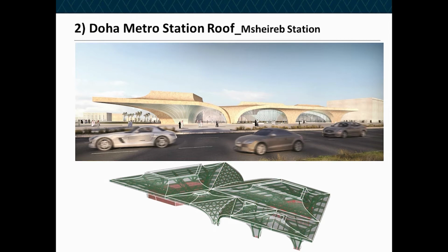And these shapes here are going to be clad in natural stone, and within that there needs to be a steel frame to support the spans of up to 30 to 60 meters, depending on where you are within the structure. So this is our steel frame in green underneath this kind of translucent shell.